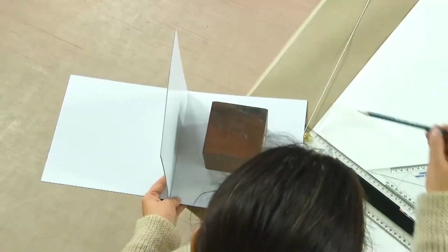But before I start to draw, let us explain how the movement of the solid is going to happen by taking these solid examples. So, we have this reference plane, and let us assume that we have a cube which is kept with us. Now, what happens in simple position is that this cube is kept like this, and we are assuming that the axis of this cube is perpendicular to HP and parallel to VP, which is what we had seen yesterday.